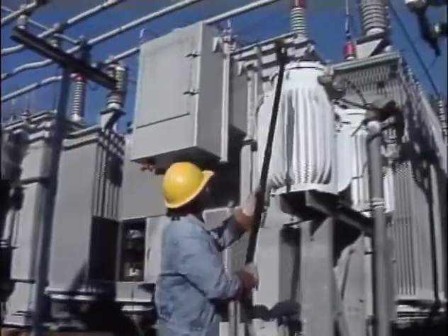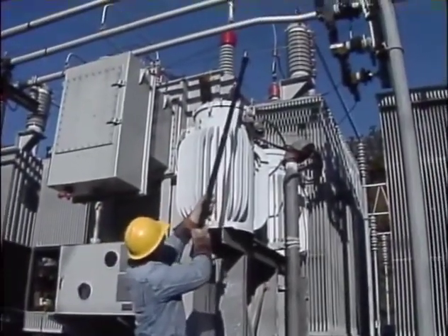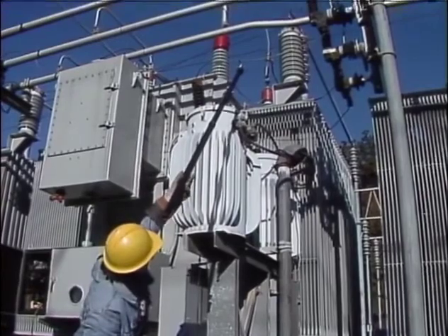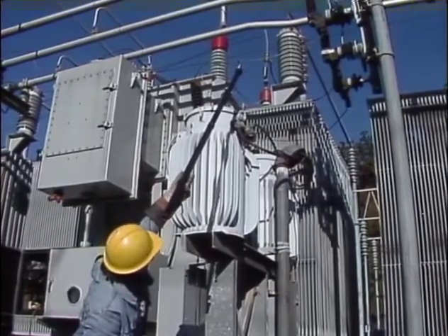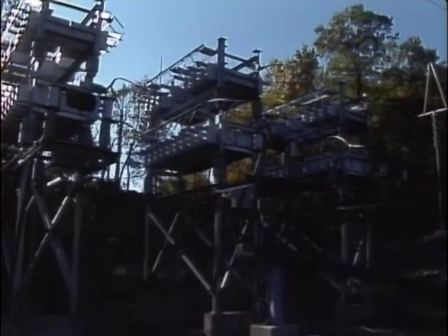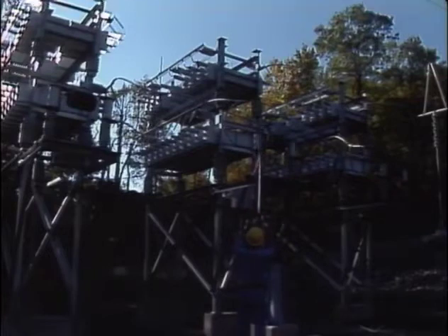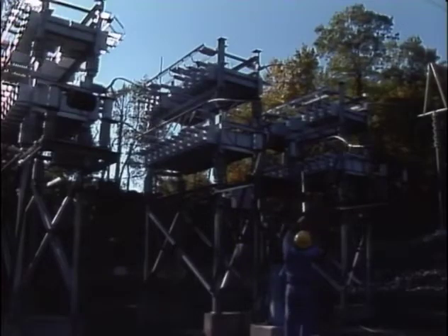Here, a worker is making sure that a glow stick works on a circuit that he knows is energized before he uses it to test a capacitor bank for dead. The tube lights up, indicating that the circuit is energized and that the glow stick is working. Next, he tests each phase of the capacitor bank. If the tube doesn't light up, it indicates that the bank is not energized by an AC source. It doesn't tell whether or not there is a charge remaining in the bank.